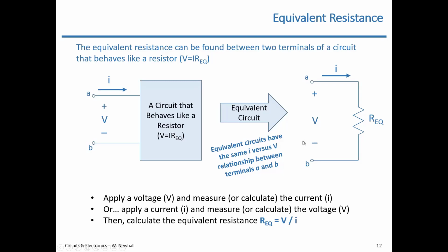If you needed, for example, a resistance of 100 ohms to handle 2 watts, but you only have resistors rated for 1 watt, then you could take 2 resistors. We'll see this in a second. Take two 50 ohm resistors, put them in series, and get a 100 ohm resistor. If you work through the voltage division, you'll see that each resistor would dissipate half the power of the total amount. So you can divide the power up among resistances. That's one thing you can do.